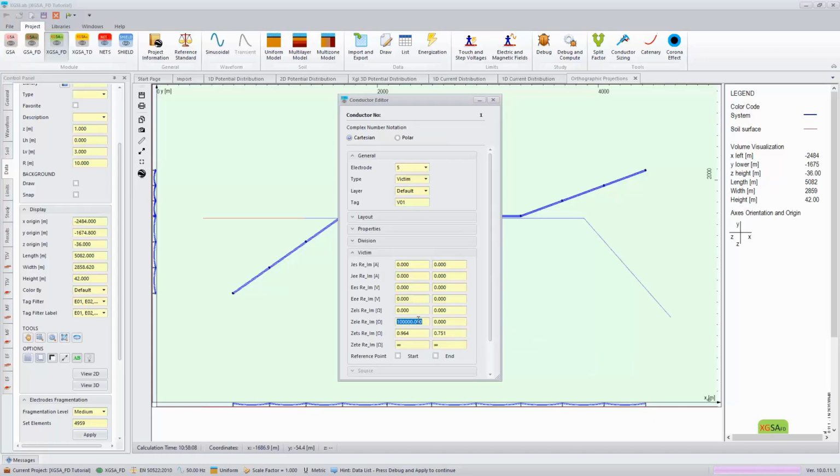So we'll remove this relatively large impedance, and we're going to modify our impedance at the end of my pipeline conductor at this point to represent an arrestor firing and operating and the equivalent impedance or grounding system associated with that point.